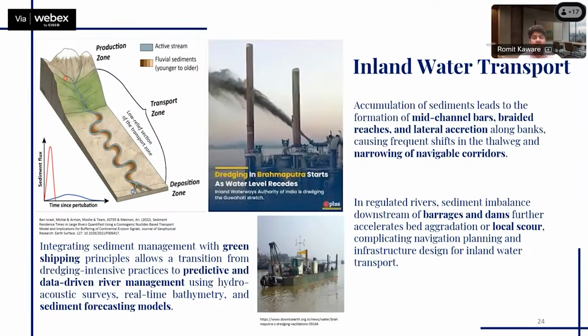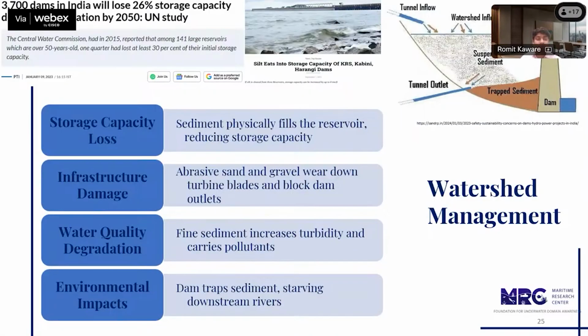Now, again, this sediment management has importance in inland water transport as well. So, in order to have proper navigable waterways throughout the year, we need to have a certain draft over the year. Now, excessive sediment supply from various sources, or say from floods, or if water is released through the dams, how that affects the sediment supply needs to be really looked into. So when I talk about this sediment trapping by the various reservoirs, we are concerned with watershed management. Now what might happen is that a lot of large reservoirs or dams on the river systems might entrap these sediments.